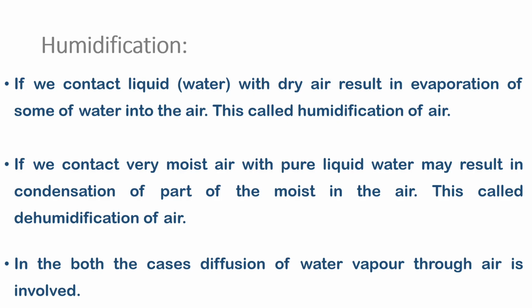And dehumidification is the opposite of humidification: contact of very moist air with pure liquid water, which will result in condensation. So some of the moisture will condense, and the liquid droplets will fall down. So this is what is meant by dehumidification. In both cases, it happens because of the diffusion of water vapor through air, and the driving force is concentration. It goes from high concentration area to low concentration.